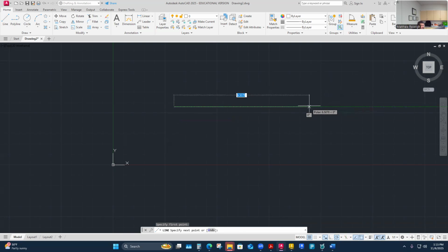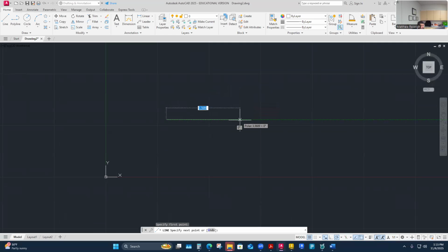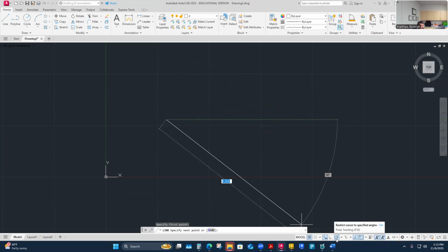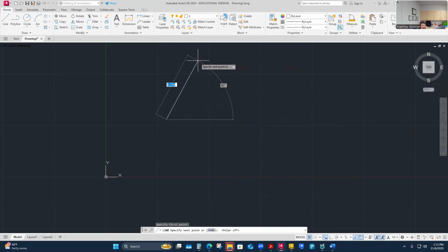Here's a line. I've left clicked at any point here. When we draw things in true vertical or horizontal alignment, I have this green thing showing up, snapping to those increments. I think it's because I have snap tracking on, or maybe my ortho, one of these. Let me turn them off. I don't know, this one first. If I turn that off, I lose that green tracking. So if you pick a line and it's not snapping to anything, it's hard to draw accurately.